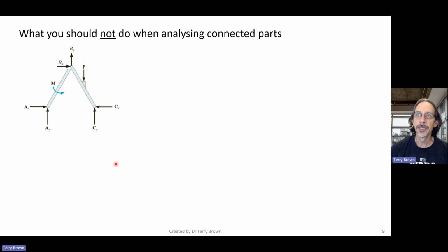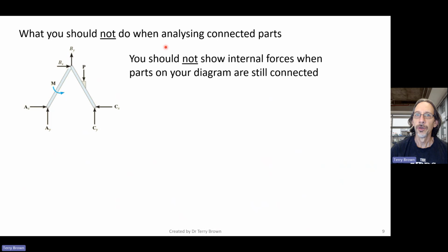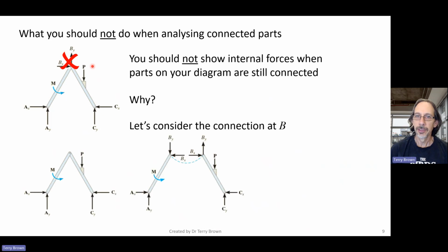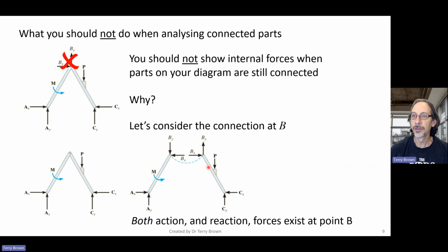What you should not do when analyzing connected parts is what I've shown up here. Do not do that, because this is not all that exists here. You're not telling the whole story if you put forces like this on your free body diagram, because you have equal and opposite forces acting there. So don't do that. The forces on both sides exist together.